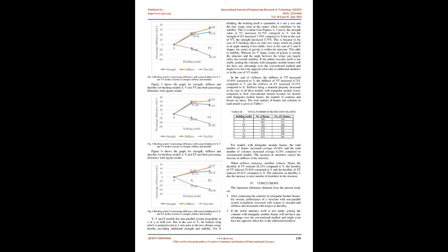Analysis were done and sections were finalized. Response spectrum and pushover load cases were defined to conduct pushover analysis. Base shear versus displacement curve was obtained from pushover analysis. The readings obtained from the base shear versus displacement graph are yield displacement, dy, ultimate displacement, du, yield base shear, Fy, and ultimate base shear, Fmax.